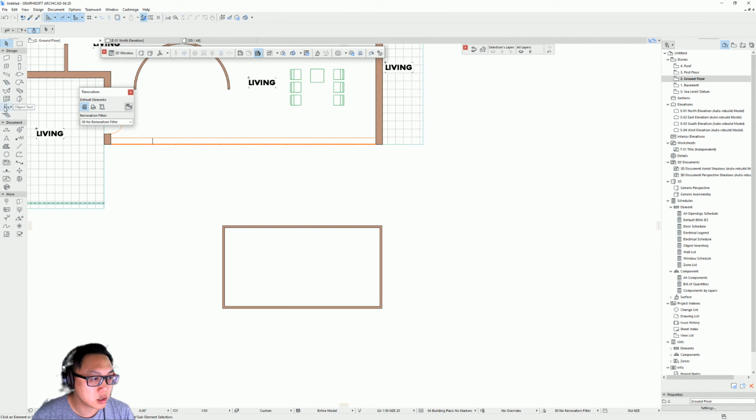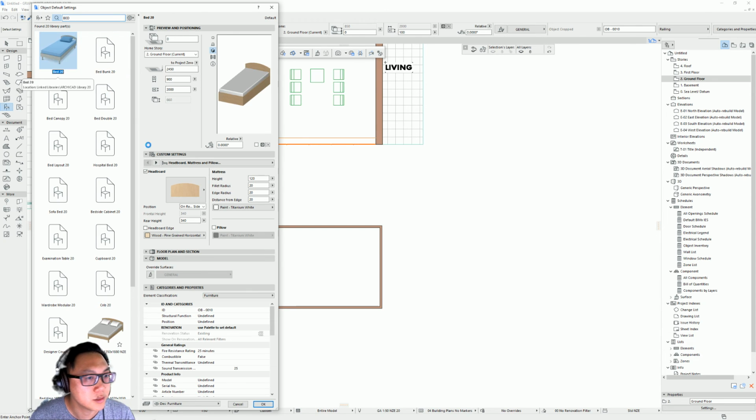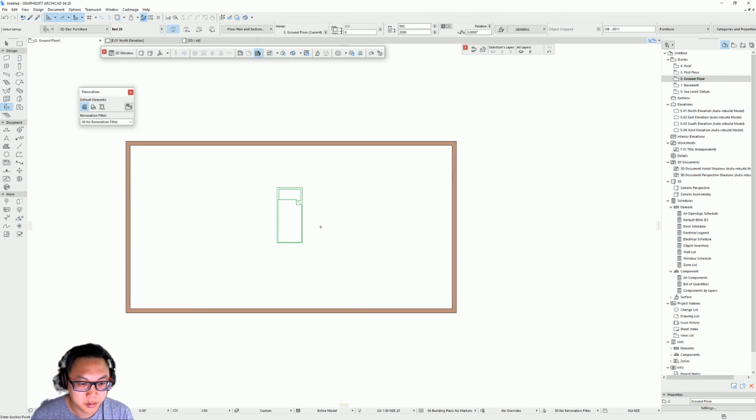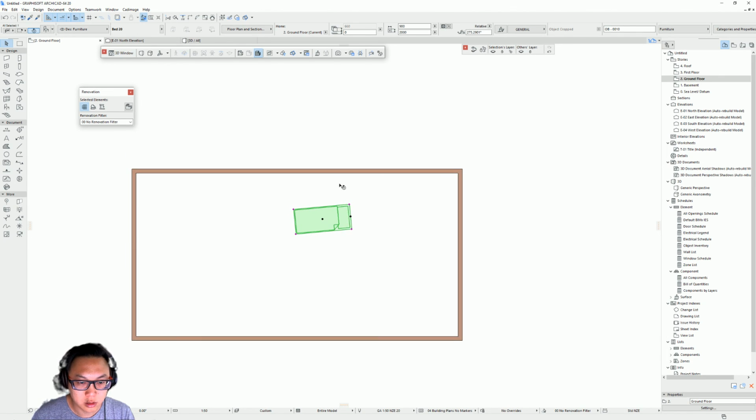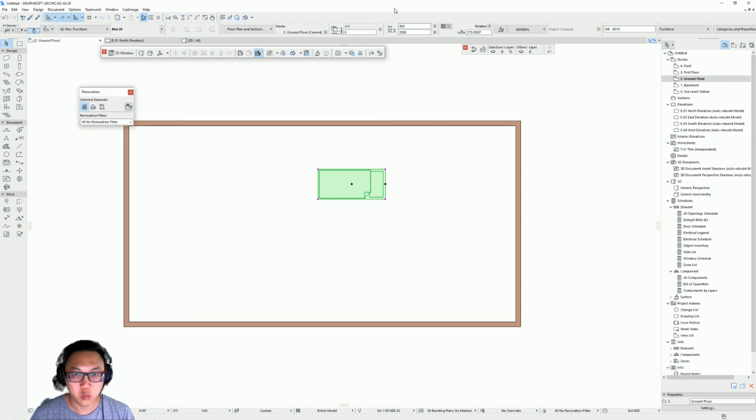And then if you want to place some object, go to object tools. Let's say I want a bed, just take a bed here, press OK, done, you got a bed. And you can move it around by pressing Ctrl D. You can rotate it if you click on a center, or even on the sides. You can rotate it to either angle you want. If there's no right angle, you can see here 275, you can just click it here to, I think it's 270. Yep. If you want to resize the bed here, 2.4, make it longer.